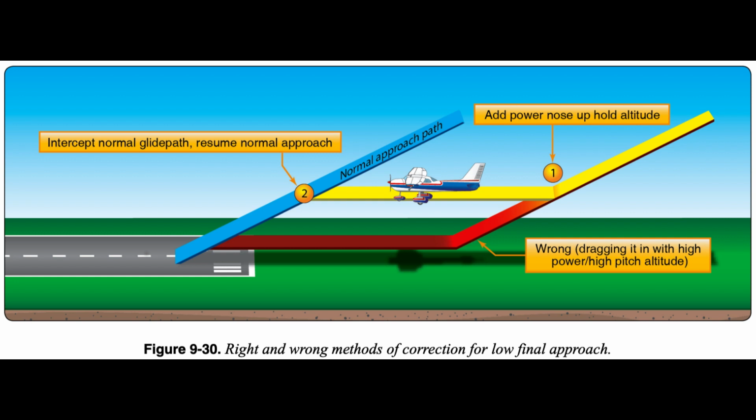The pilot should not increase the pitch attitude without increasing the power because the airplane decelerates rapidly and may approach the critical AOA and stall. In addition, the pilot should not retract the flaps since this causes a sudden decrease in lift and causes the airplane to sink more rapidly. If there is any doubt about the approach being safely completed, it is advisable to execute an immediate go-around.